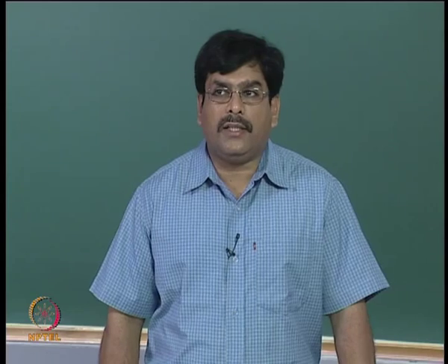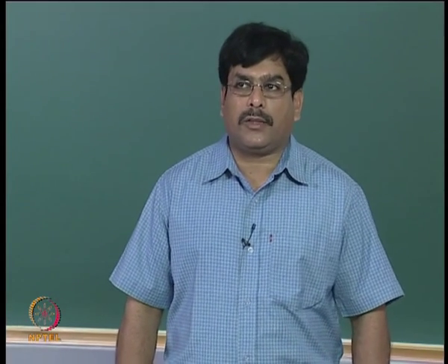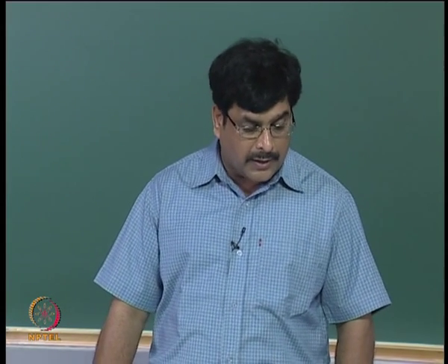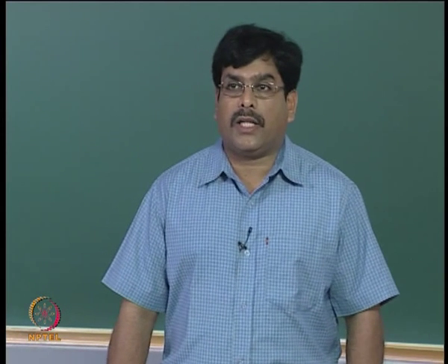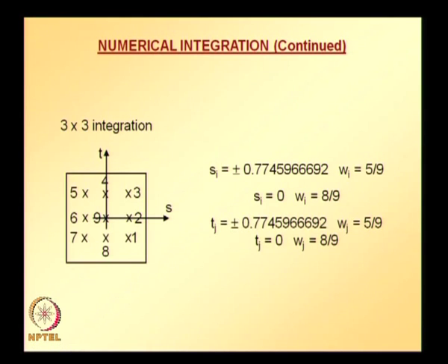Calculating the weights as I explained, weight in the s direction times weight in the t direction, we get weights at all the points, and by combining the coordinates in the s direction and t direction, we can get the coordinates of all points for this 2 dimensional integration. So, a similar procedure can be extended for any order of integration.